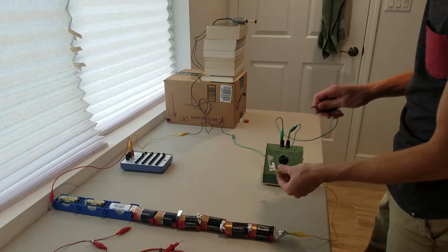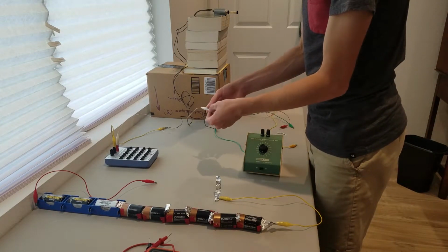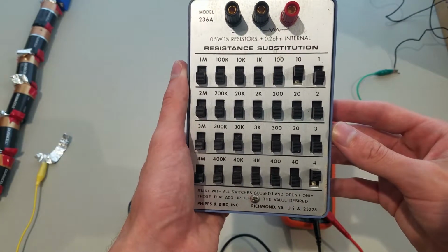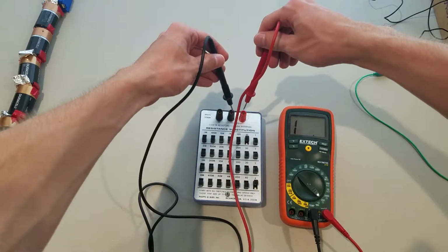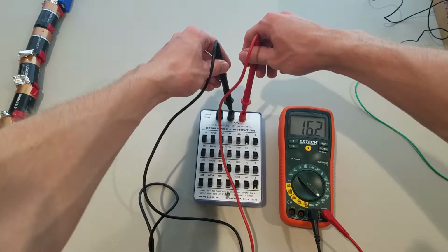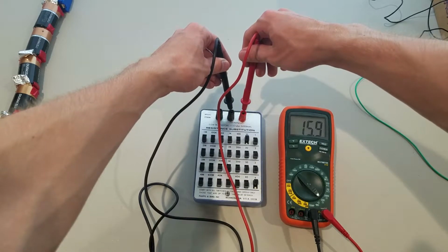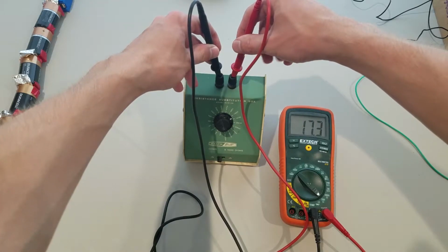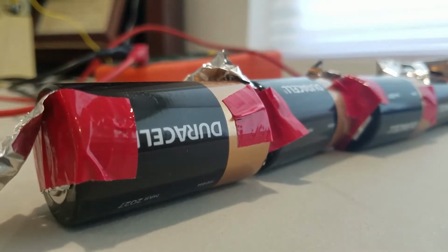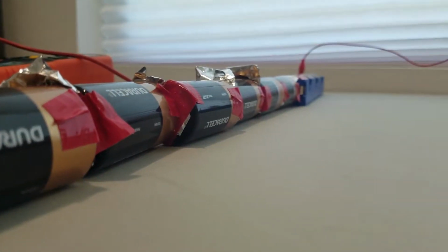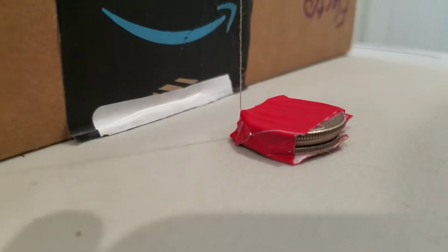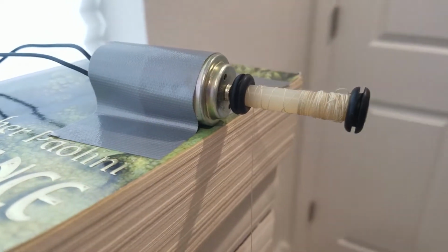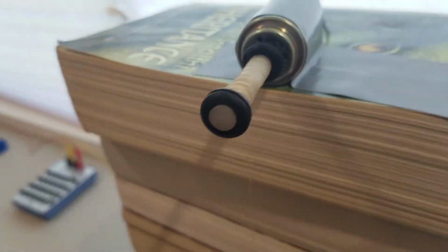Before getting into the problem, I want to go over the elements I will be using for the real demonstration. Resistor 1 is a 14 ohm resistor, which I confirmed using the multimeter, although it displays a larger number because it has its own internal resistance of about 2 ohms. Resistor 2 is a 15 ohm resistor, again confirmed using the multimeter. There are 9 1.5 volt D batteries in series that power the circuit, and the mass consists of 3/4 taped together. Finally, the motor. Alright, now let's get into the problem.